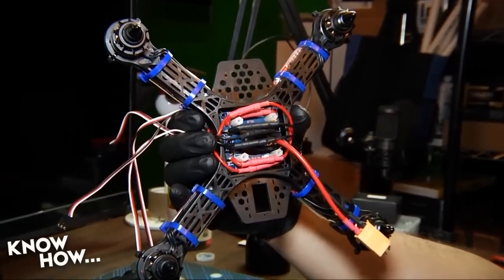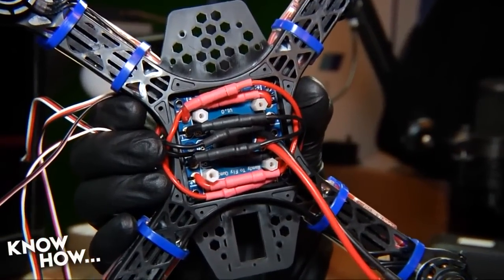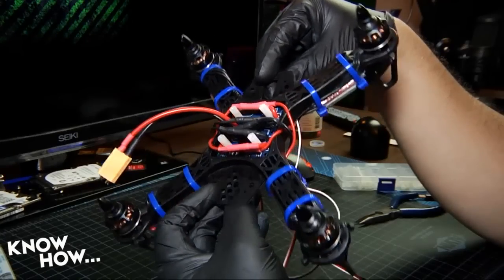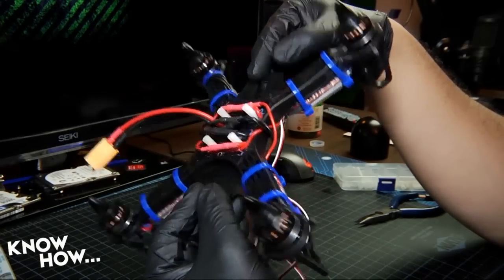Connect your ESCs to the power distribution board. I prefer to connect across the board to neaten the appearance of the harness. Just make sure you match lead colors, and you might as well double check to make sure that you've soldered black into negative and red into positive.